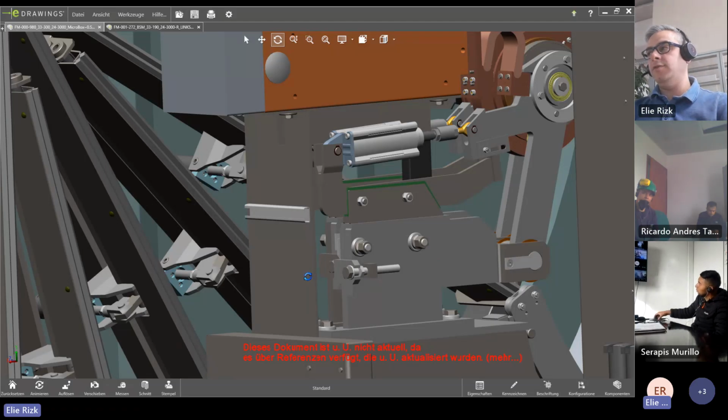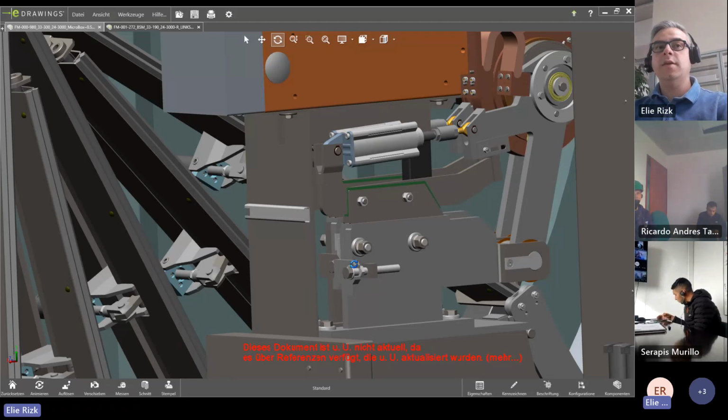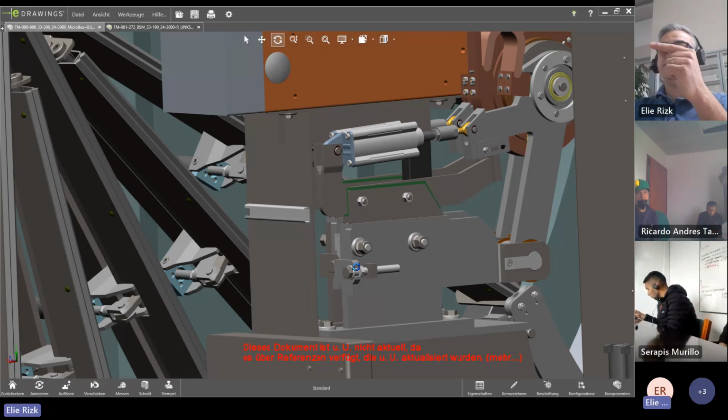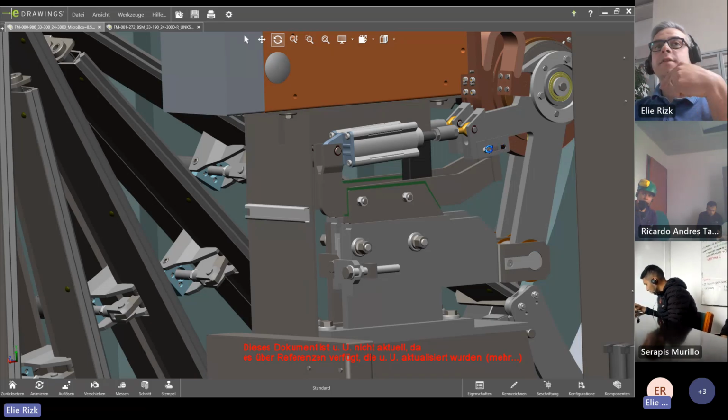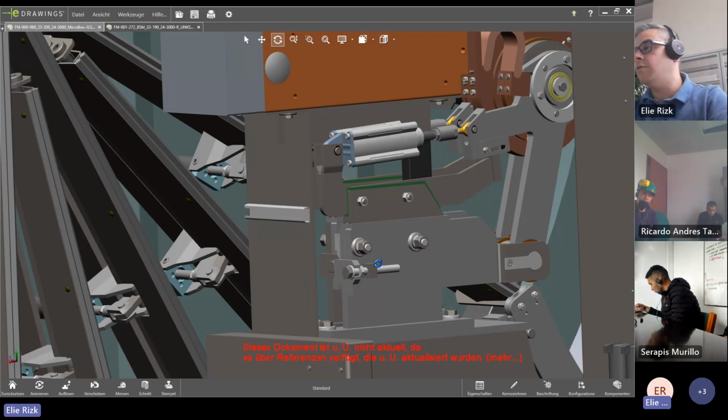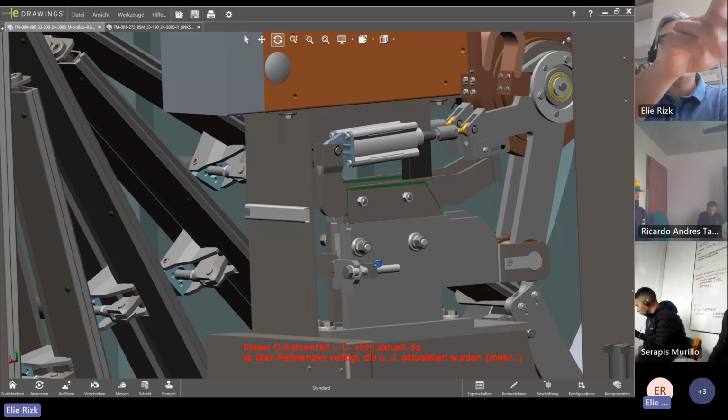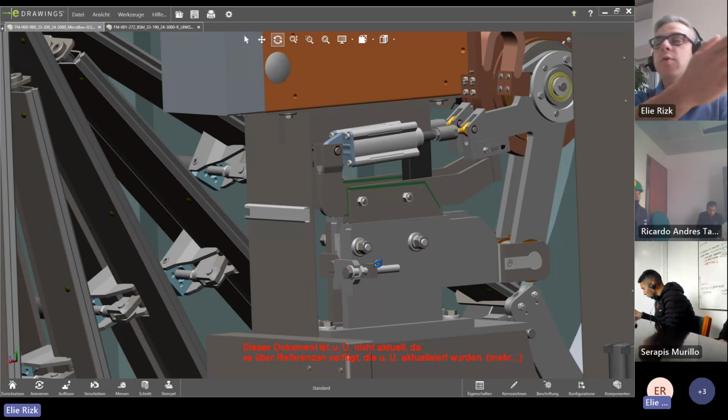So in this case, when you don't have a good contact, when you put the longitudinal wire and then the winding wire and you close the electrode, and the welding cage is in position and the contact roller is showing 3 millimeter, and still you don't have any contact with the wire, then you have to adjust mechanically the position between the contact roller and the welding roller. So you use this screw to make it a little closer or a little back when you have too much.